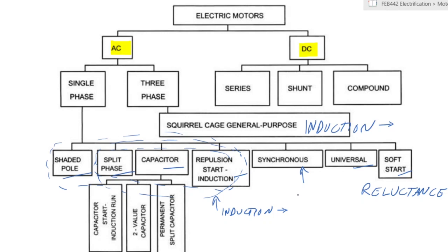The only difference is that whereas the alternator had a field and was fed with mechanical or rotational energy, and the field was rotated within some windings, for a synchronous motor you have the field applied to windings in the stator which are already electrified. So it works in the reverse of alternators.